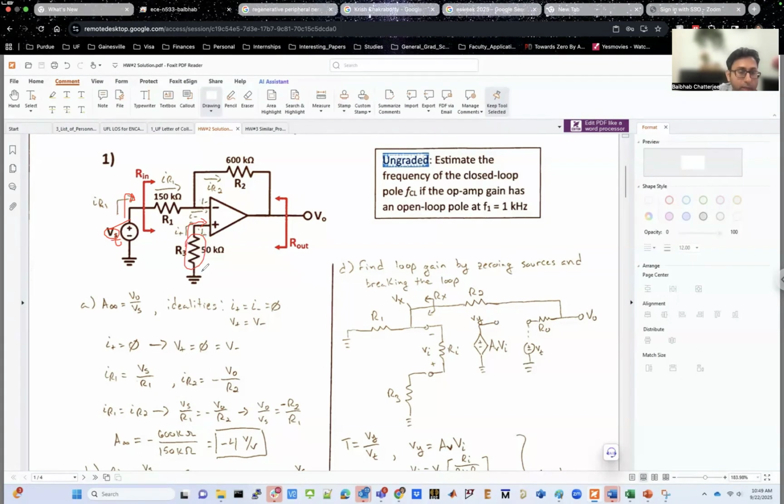So if the bottom terminal of R3 is 0, the top terminal of R3 is also going to be 0. And because it's a negative feedback, you have the virtual ground property for the op-amp. For the inverting terminal as well, you have a 0 voltage here, 0 AC voltage. So basically that is forcing the inverting and non-inverting terminals of the op-amps to be at 0 volt. Right? It does not mean that there is an actual ground over there.